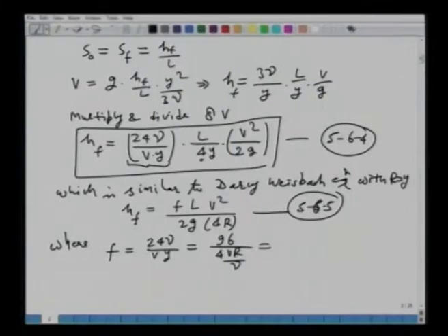Slight modifications. Then this is, as you know, what is the term in the denominator? Do you recognize this? This is a non-dimensional number, all right, Reynolds number. Okay. All right. So, this is 96 over Re, okay, where your Re is equal to 4vr over nu, okay, with r is equal to y we have already said.